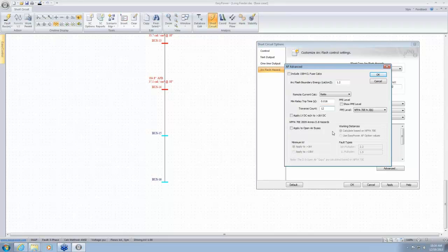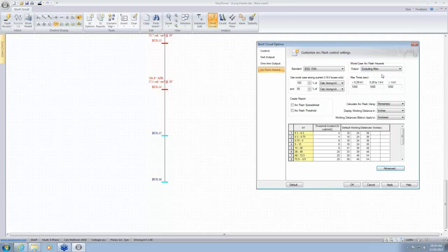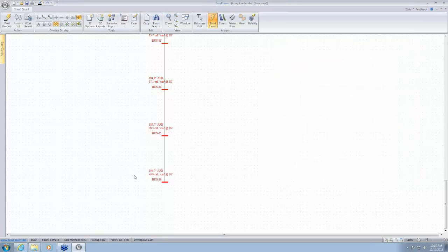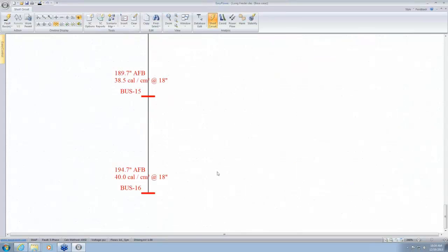So what you would want to do for such feeders is increase the count to say 25, whatever number is required. Click OK. Now I get results here. So anytime you have a long chain, just make sure you have increased the traverse count to an adequate number as per your requirements.